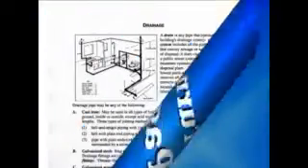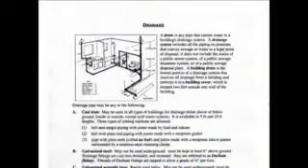Let's go on to page 25. Top of page 25, drainage. I'm going to have you highlight that very first sentence. It's the basic definition. A drain is any pipe that carries waste in a building's drainage system. Read through the rest of that paragraph, noting the distinction between a building drain and a building sewer. One is outside the building, that's the building sewer. The other is inside the building for the most part. Read carefully, see exactly where they begin and end.